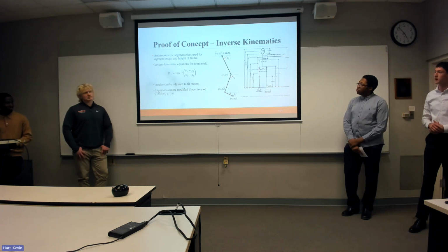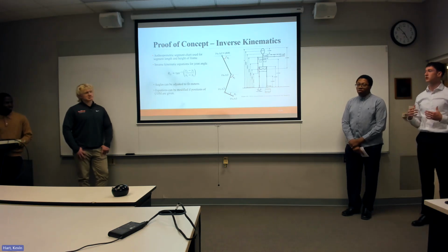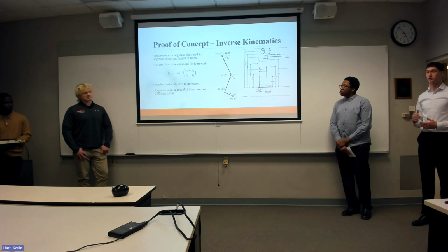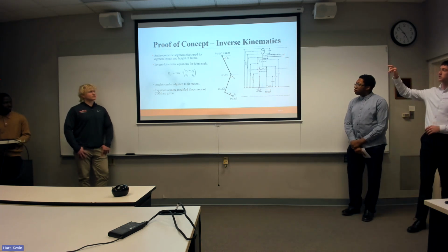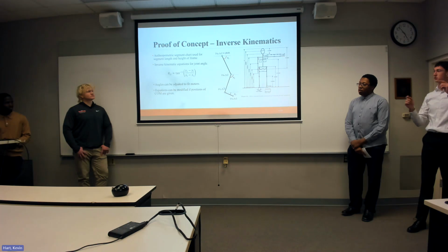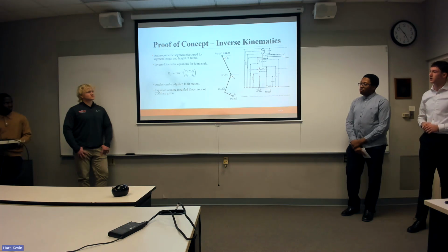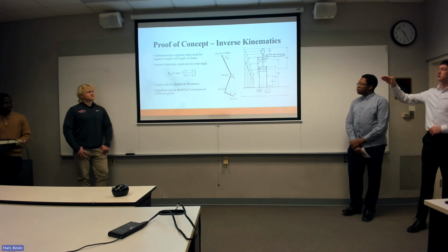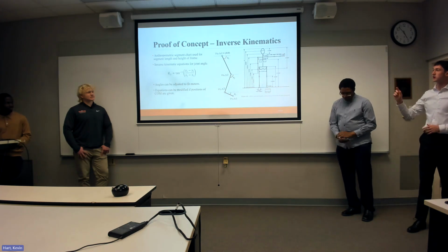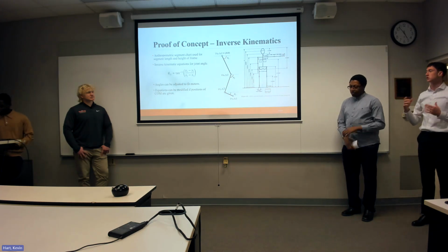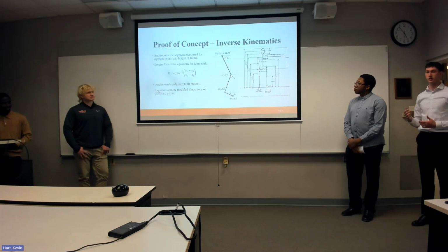And so the ones that we care about are obviously the ones on the foot, the 0.53 times the height, that kind of stuff. And then we decided we needed to determine the inverse kinematic equation used to calculate the joint angle. It basically just uses the two positions of that segment to determine the angle. Then once these angles can be seen, obviously we were going to use that diagram there. Once these angles are calculated, they can be adjusted to fit the motor inputs.